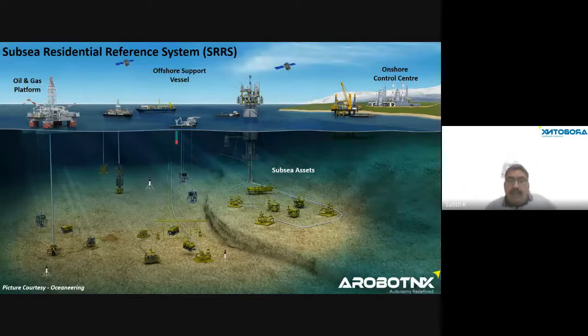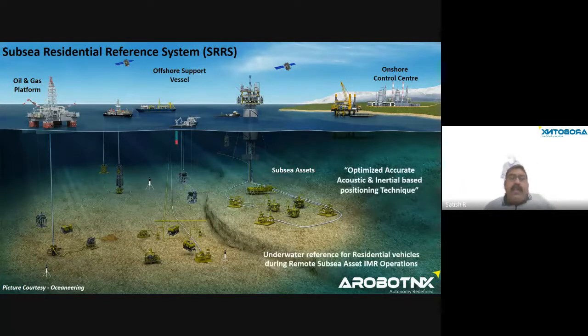and what we carried out is an optimized, accurate acoustic and inertial based positioning technique for resident and remote subsea, or RMR, operations. So it all starts from here, where we just deployed it on the seabed. Since it is long range and long term, it can be deployed for a long time, so you can even go to sleep mode. We deployed the transponders on the seabed and asked them to carry out the referencing operation for the vehicle, to carry out different tasks on the seabed.